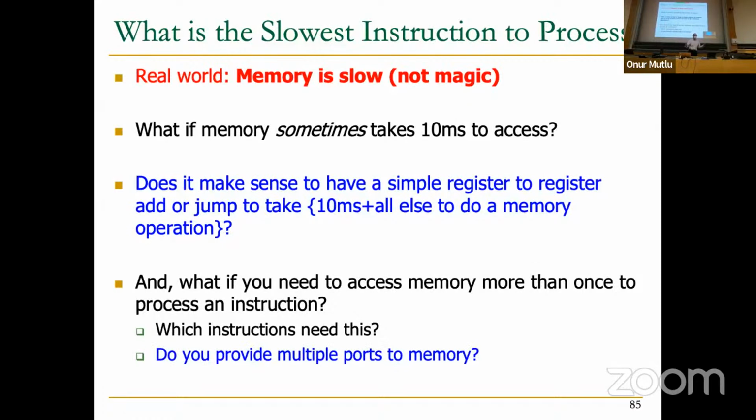You can do that, but it's a sequential process. You need to fetch the instruction so that you can figure out the registers and calculate the address before you fetch the data. The reason I'm telling you this is that the single cycle processor makes little sense in the real world. Maybe let's say no sense in the real world.